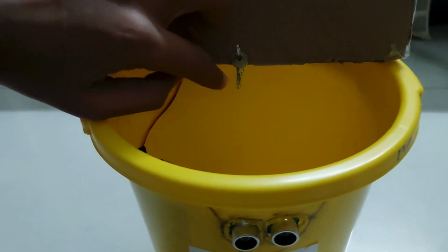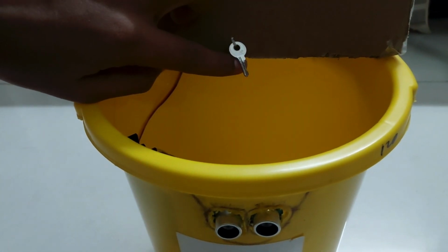And then here we can see with the flap there is a key attached, and this key will help in opening of the flap. Whenever the servo motor gets a positive signal from the Arduino, then it will turn by 180 degree, taking the thread with it, therefore taking the key with it, and the force of the key will help in opening up the flap.